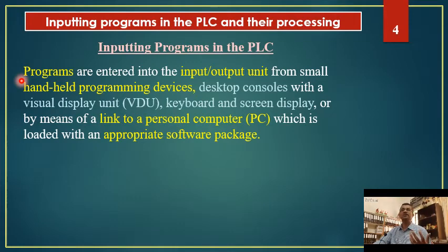And programs could be entered into the input output unit from small handheld programming device. So this is one way of programming the PLC. We may use a small handheld device, and connecting that one to the PLC, we can write the program onto PLC using this handheld programming device.